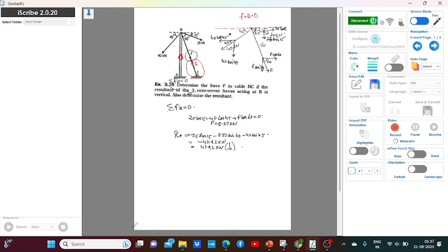This is another problem which can be asked for 4 to 5 marks in University of Mumbai as well as in other universities. You just remember about the tension forces. If anything is tied like this from this point to another point, then in this we will have a tension force. In an examination, they need not give this arrow. If the arrow is not mentioned, you have to assume that the arrow will be like this. So you just cut this part, and you draw this as the free body diagram. You remove all other things. Only forces should be there in the free body diagram.